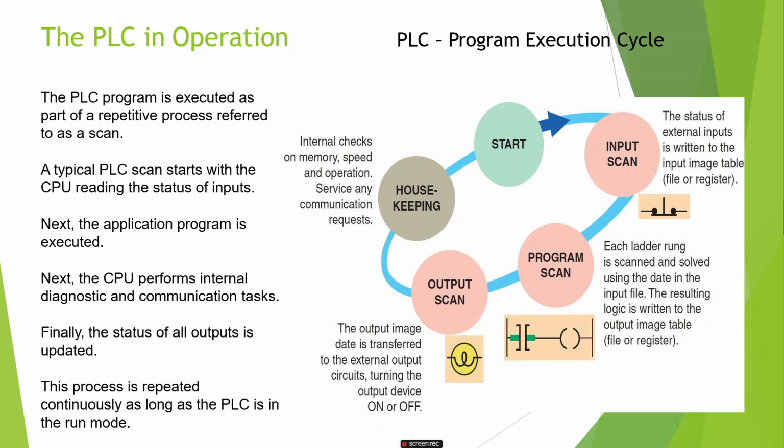Then the CPU performs internal diagnostic and communication tasks. Finally, the status of all the outputs is updated. That is called the output scan. This process is repeated continuously as long as the PLC is in the run mode.